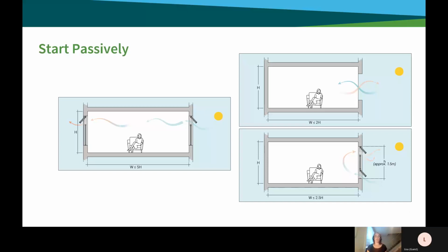And while you can get some natural ventilation on a window or on a single facade, air movement is greatly enhanced when you use cross ventilation strategies. So putting a window or an opening at opposite or different sides of a unit or a space. This can really help achieve thermal comfort for your occupants for significant portions of the year.